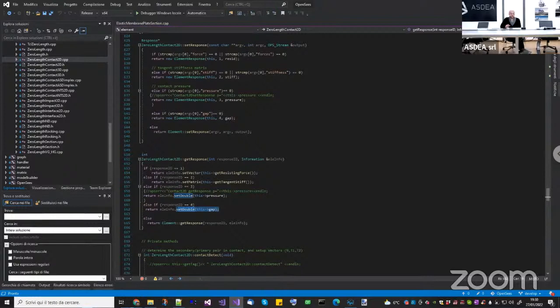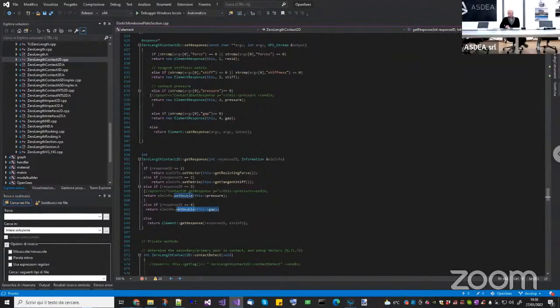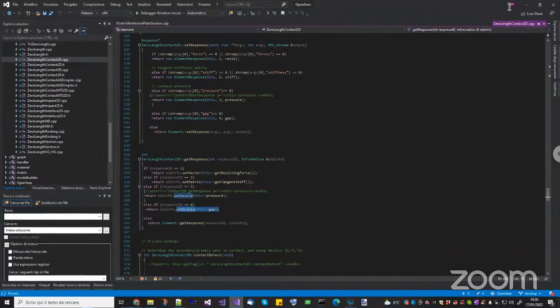Actually, I have developed this code for masonry infill, which takes into account the biaxial interaction. But drawing it contains a lot of zero length elements. So drawing it manually in STKO is very difficult, as I have to develop it for each frame. Like if I have a 10-story building, that also 3D. So is it possible that I can add that TCL code to the already developed model in STKO? Like we have already one masonry infill code that you have developed, but that is in Python.